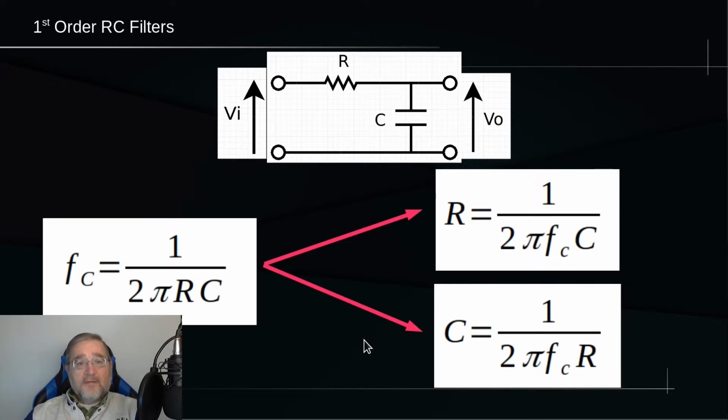You arbitrarily define the value of either R or C, just one of the two, and then you use the appropriate formula to calculate the other value. It is that simple. In reality, however, you do not really choose arbitrarily one of the two values. In general, you make a list of all possible values that are okay to use in the circuitry that the filter is connected to, and then, for each of those values, you calculate the other one and make a small table. And then you choose the pair of R and C values from this table that works better for you.